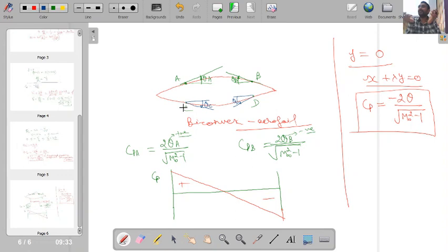And this correlates with the theory also. From theoretical understanding we know that here pressure will be acting in the positive x direction, so here Cp should be positive. On the back end pressure will be acting in the negative direction. So here my area vector and pressure vector will be in opposite directions, outward normal and pressure. So that's why the Cp value should be negative. So it is making a relation with theory also.